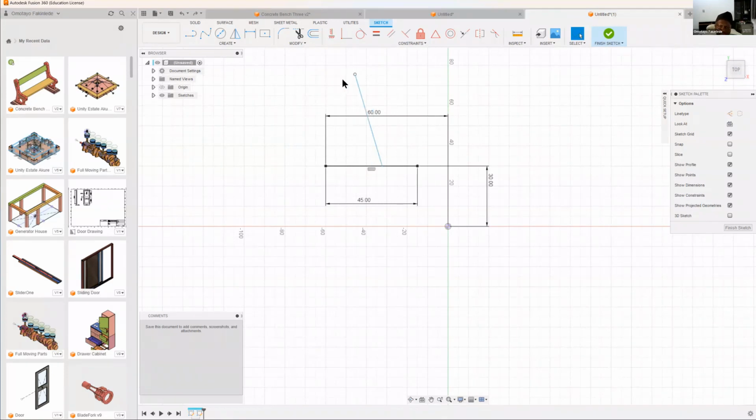So I can decide to create an angle, to take a dimension, and the dimension I want now is an angular dimension. I take this line and this line. If I take these two lines, you can see I'm able to set what that angle is. If I make that 60 degrees, so that is 60 degrees. So I've chosen this to be inclined at 60 degrees. And this is still blue.